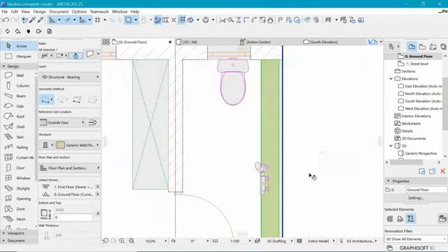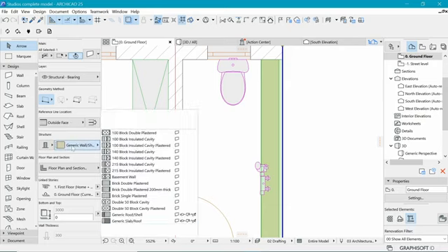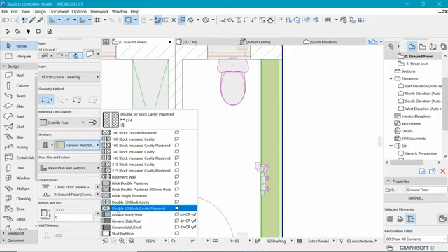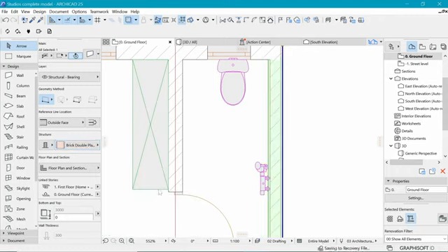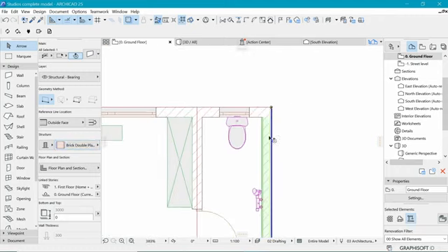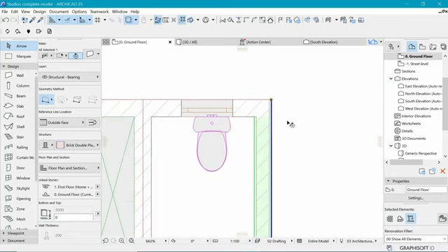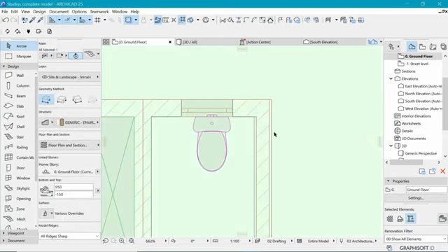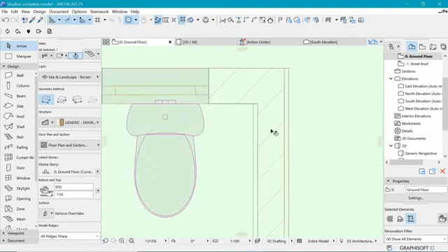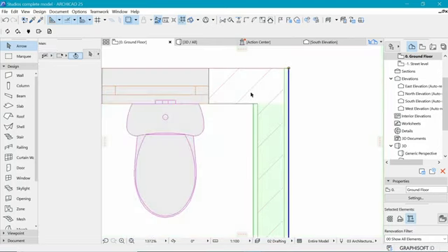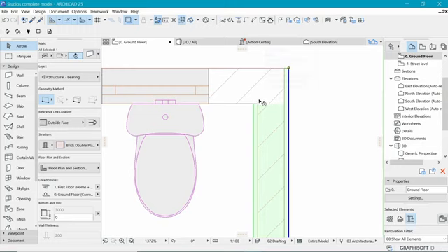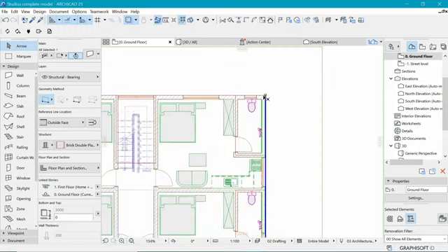And we say okay. Of course nothing changes, and that's because we have to select this wall and choose within these options for double plastered brick, which should be somewhere here, brick double plastered, but the one which is 200 millimeter thick, the one we have just created. And just like that, we have ourselves a nice wall here which has a brick and a plaster on either side. Pretty cool. And then we want to change all our exterior walls to be like that.